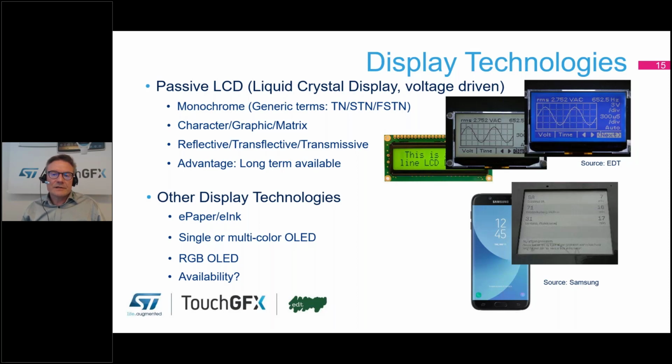And then, of course, we cannot forget and overlook the e-paper technology, which is good for signage, warehouse price tags, etc., where you don't need to update the information on the screen very often because it requires some high power to update the screen, and then you can take off the power and the image will stick on until you update it again. That's a benefit. On the other hand, you can't read it if there's no ambient light to reflect it.